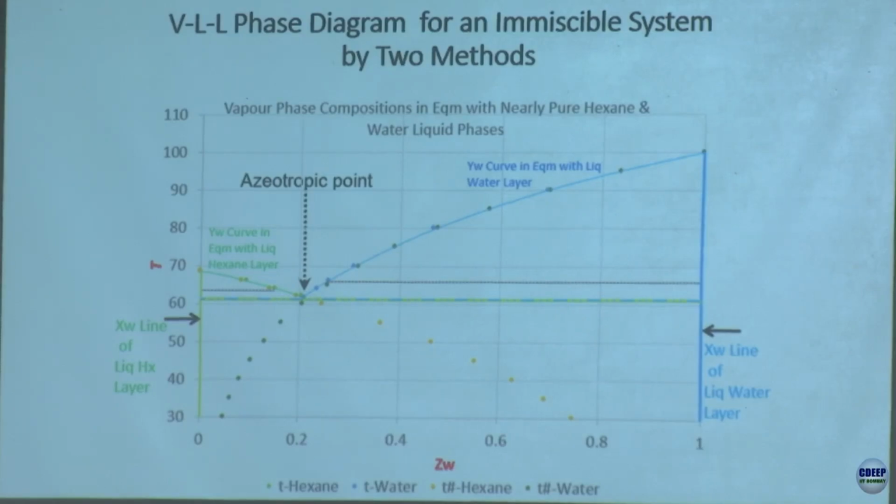One has to be cautious, however, while using the latent heat and boiling point data over an extended temperature range. If the two components' values of boiling point are extremely different, then you may have a problem that this particular curve, if this boiling point goes here, then it might go even outside this. So that method does not work when the boiling point differences are huge. But generally otherwise, if the boiling point differences are closer, both the methods work well.